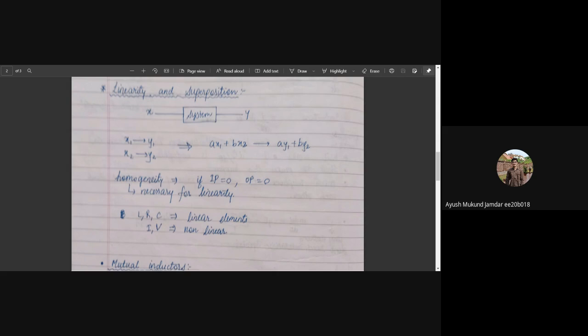Basically, a passive element is one which does not generate or modify the nature of voltage or current. It can only dissipate, store, and release the stored energy. And yes, resistors, inductors, and capacitors are passive elements. They may need an external energy source to operate, but I'll reiterate on that again. They dissipate, store, and release the stored energy. They cannot generate or modify the nature of the energy, which is in the form of current and voltage.